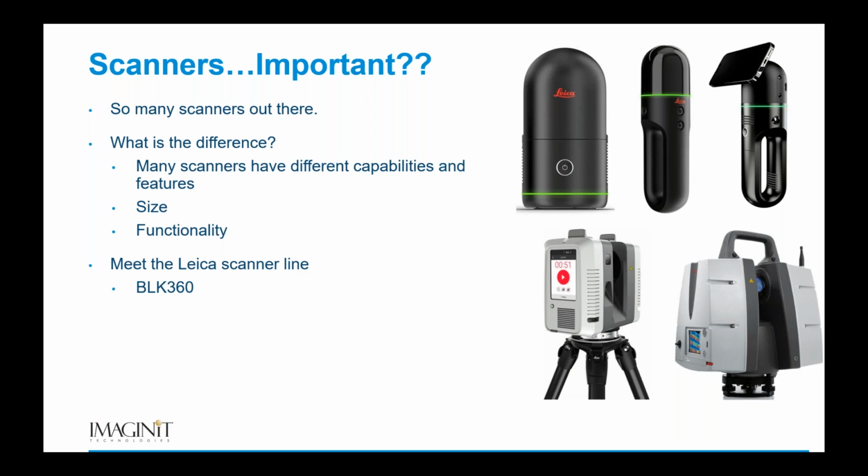Okay, these tripod-based scanners, even though we have to agree to the registration, the stitching together, it's kind of automatic with the Leica BLK 360. The app tells us, hey, this all goes together. Are you sure you want to put it together? We simply agree with the app if we do. Done. Those two scans are stitched together.